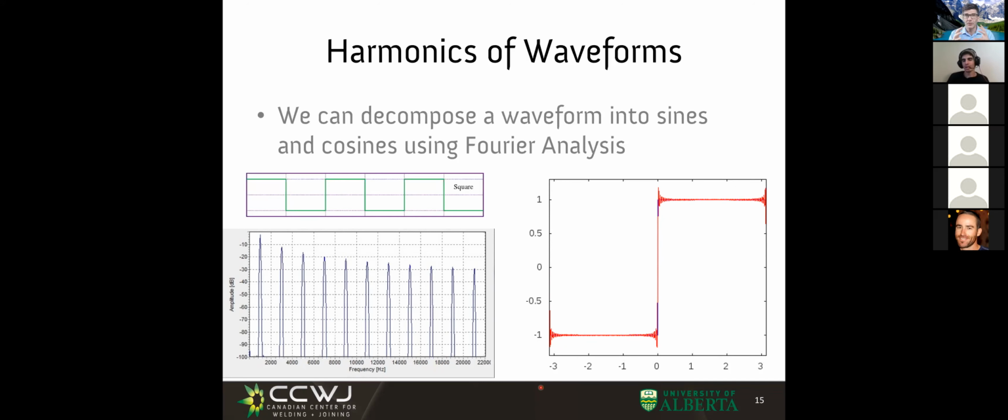If you get the resonant frequency right, you can encourage the detachment of the droplet at lower currents, right? The engineering of waveforms in welding is amazing and is today done mostly inside the companies, and they sell you waveform number 1, 2, 3, 4. You don't get to choose other than 1, 2, 3, 4.